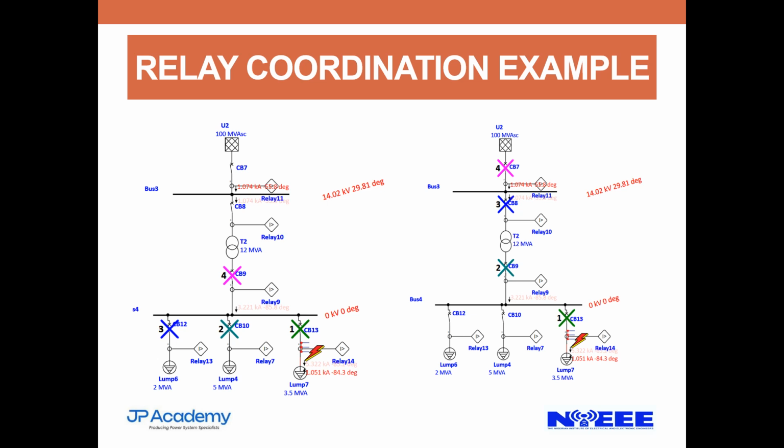So if we are looking at fault isolation, we are only going to experience a trip at this point here. We are actually going to see the illustration using ETAP software in tomorrow's session. Fault isolation is to isolate only the faulted place. Relay coordination is to see how all the relays in the system will operate one after the other, the primary relay and the backup relay. That is relay coordination. I don't know if the point is clear.